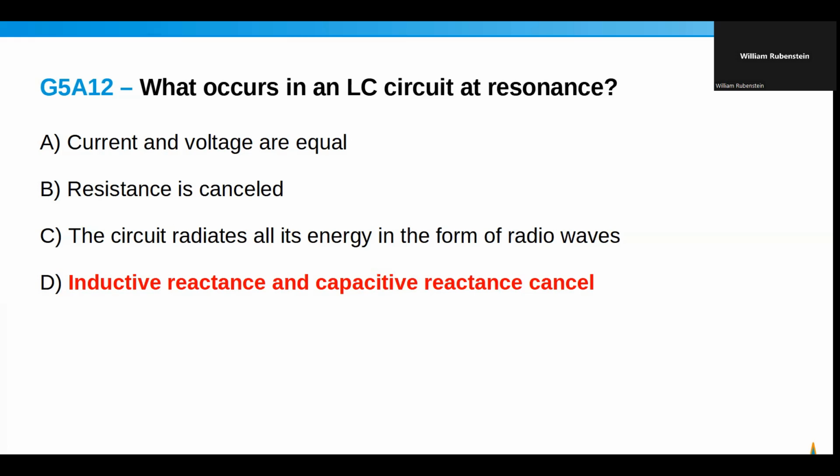And that's true whether it's parallel or series. It's going to be whatever the actual resistive value is. So even if it's parallel, where your LC circuit is going to be very high impedance, it's a high impedance in parallel with that resistor. So the value is essentially going to be whatever the resistance is.